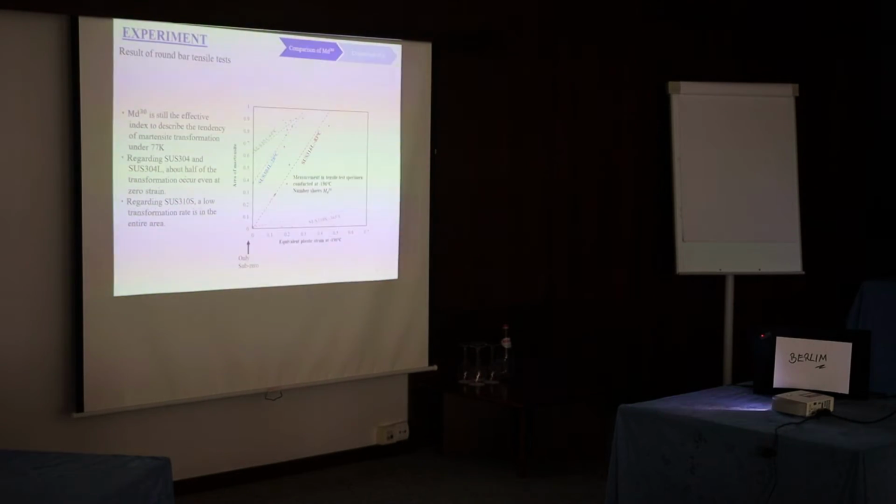And regarding 304 and 304L, about half of the transformation occurred even at zero strain. On the other hand, regarding the 310S, a low martensitic transformation occurred in the interior area.